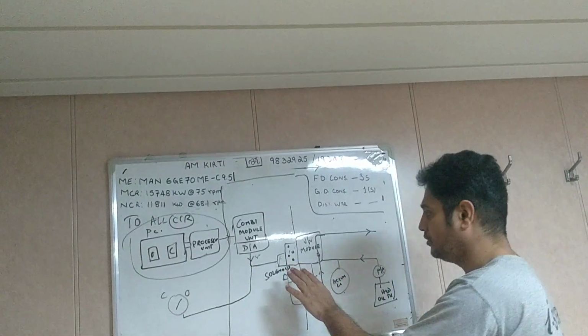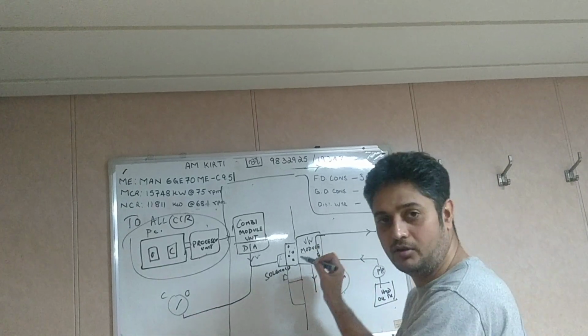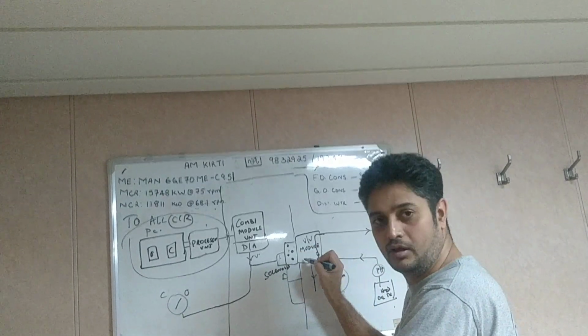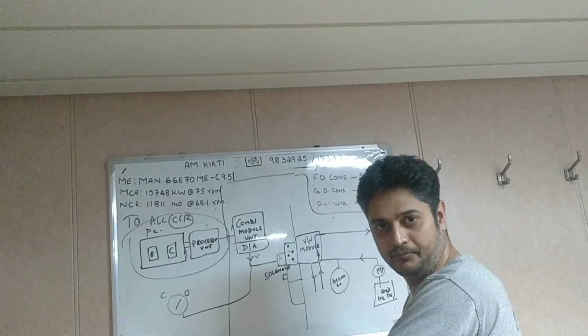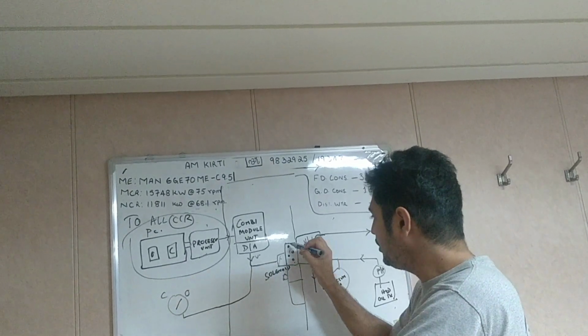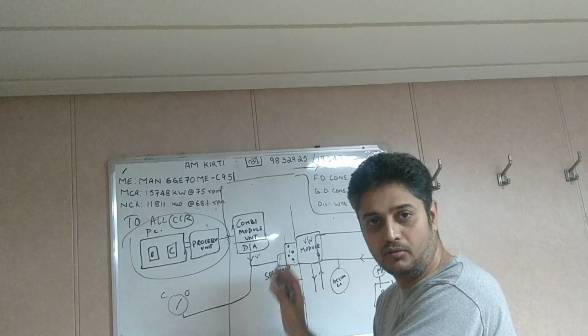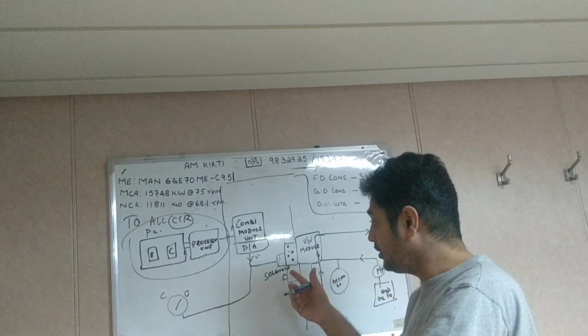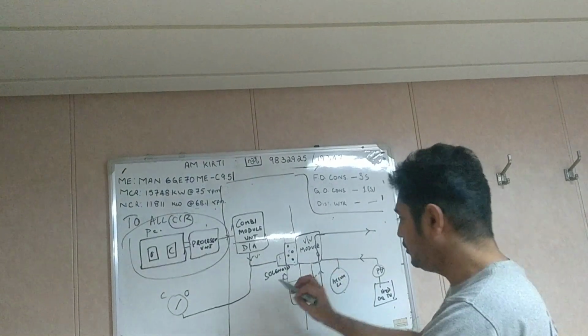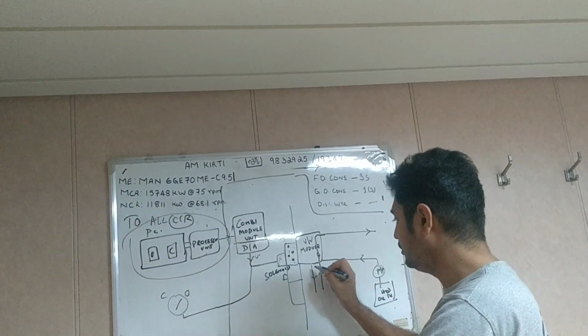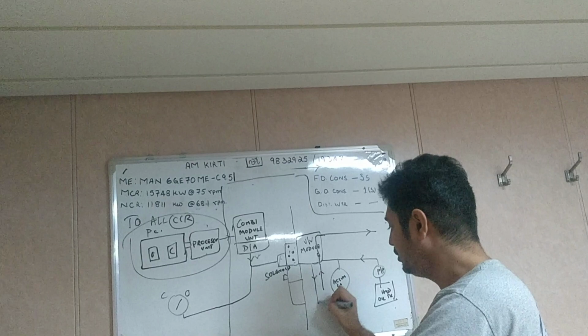Now you got an idea, no? This valve module has a spool, which is integrated with the proportional. So the whole unit is a direction control valve, activated by the solenoid valve. This is what is happening. When you give the open command, the pressurized oil goes.